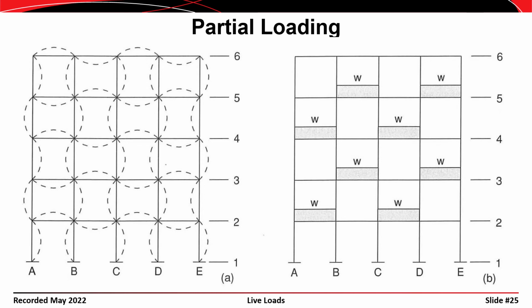There are continuous frames in steel buildings. However, if you look at a moment resisting frame that's part of a lateral force resisting system, then you would have a similar situation to what's depicted here. It's certainly more commonly encountered, though, for concrete structures than it is for steel structures.